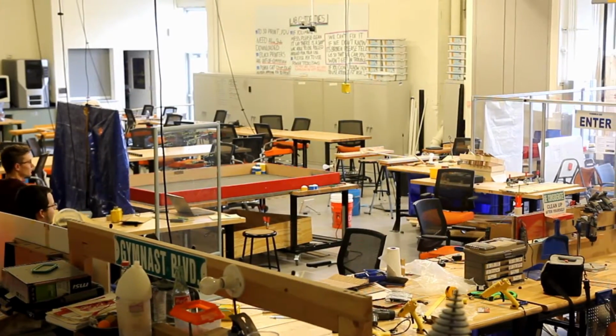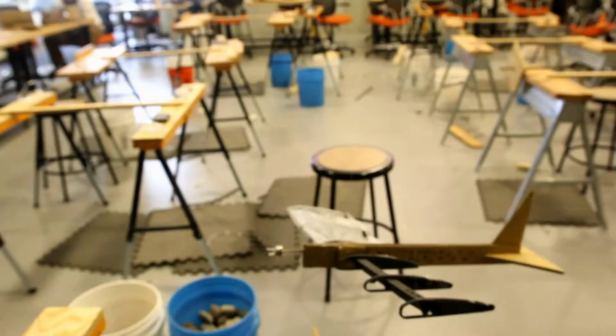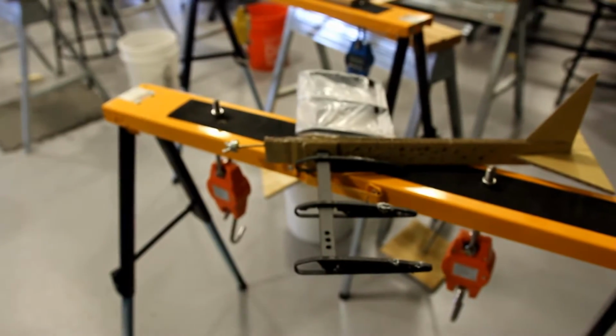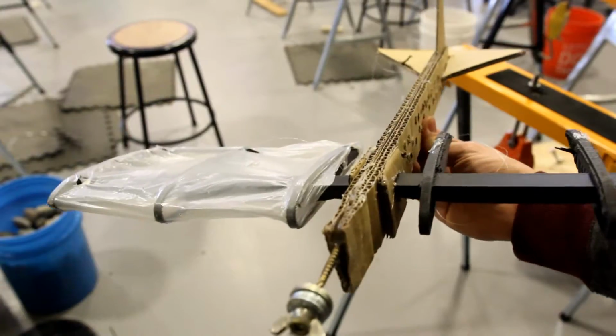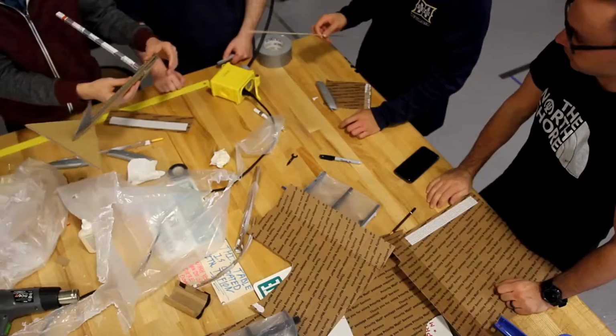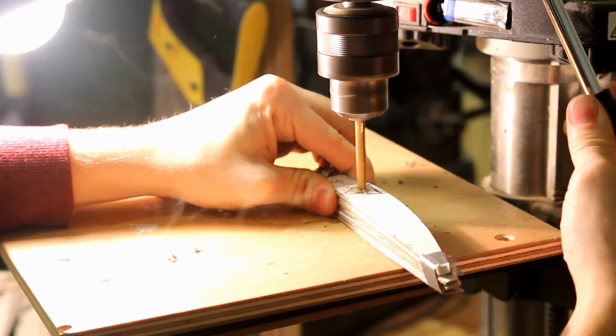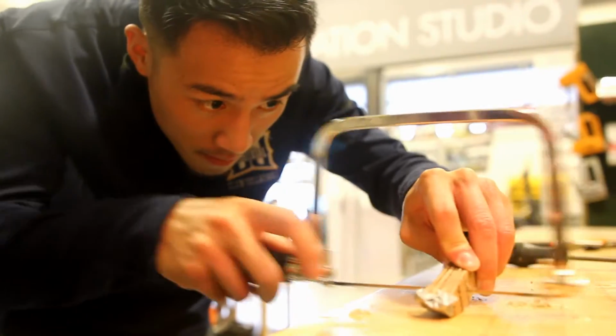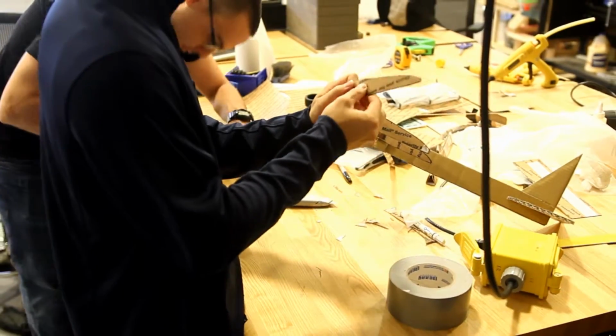Although we had several stable flights, we concluded that the additional weight had produced a much too small glide to descent ratio. Additionally, we found that our manufacturing process of putting the skin over top of the wings was allowing some air to get caught inside of the wing. In the next iteration, we'll address the weight and the skin manufacturing process.